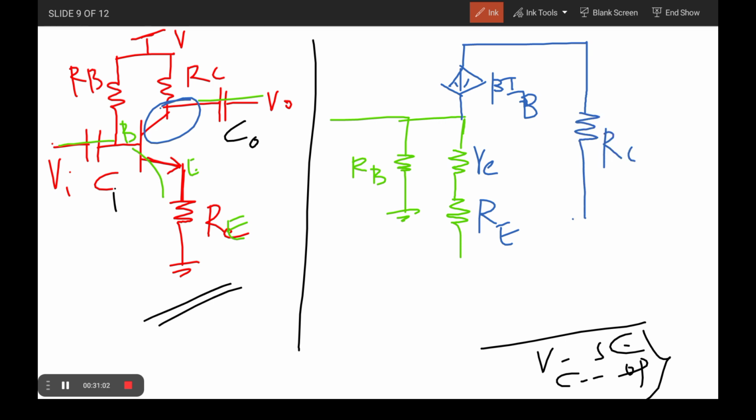So this is the equivalent model representation for the circuit. I think it's very easy, guys. The input section can be represented as a resistance, and if there is any other resistance, these two resistances are connected in series. The output section acts as a constant current source. If there is any resistor, you just have to connect it in parallel, because a current source and the corresponding resistance are connected in parallel only, right? So that is the representation model for this one.